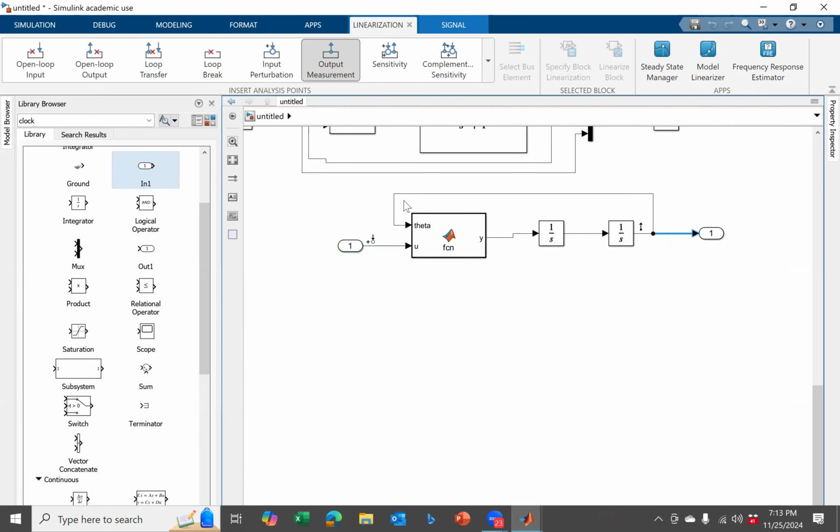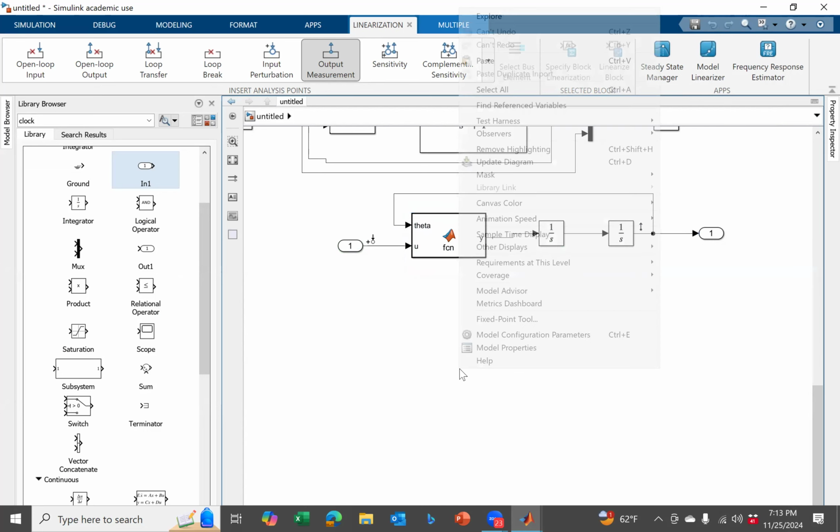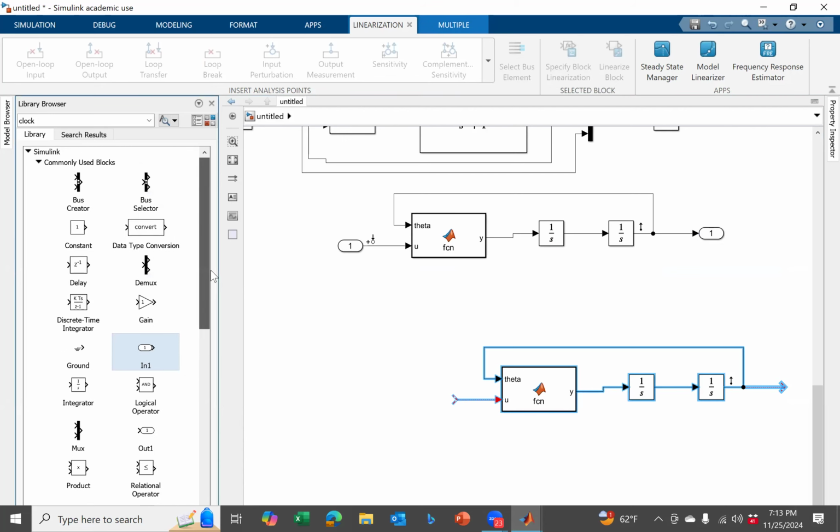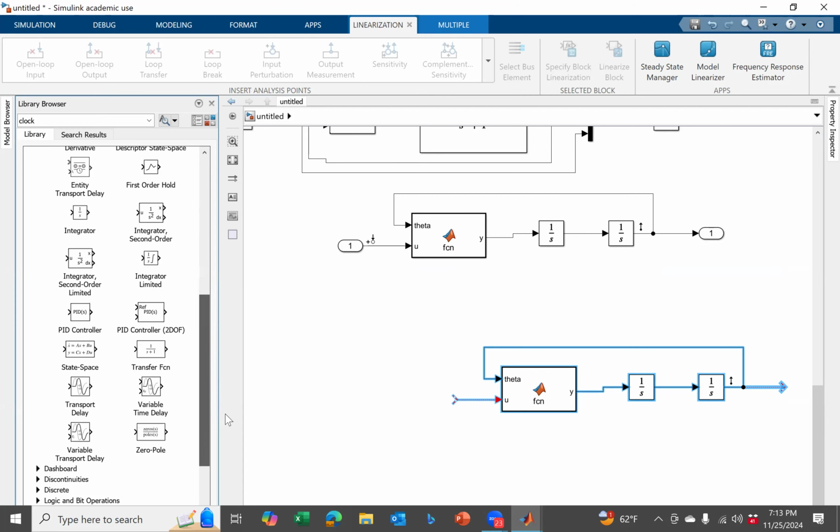Now the question is, how do we do all this? All this mathematical jugglery is great. Now, how do we design the controller? And again, to design the controller, I'm going to go to the PID block, attach the PID block over here.